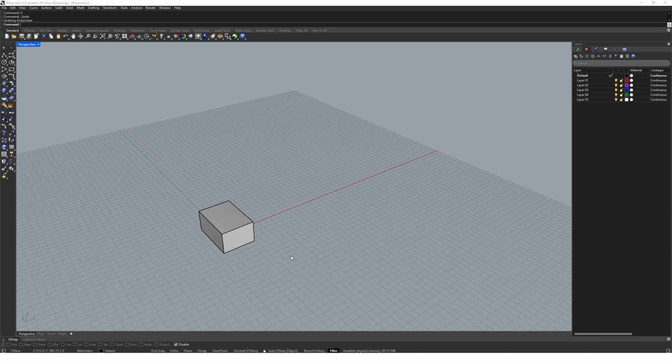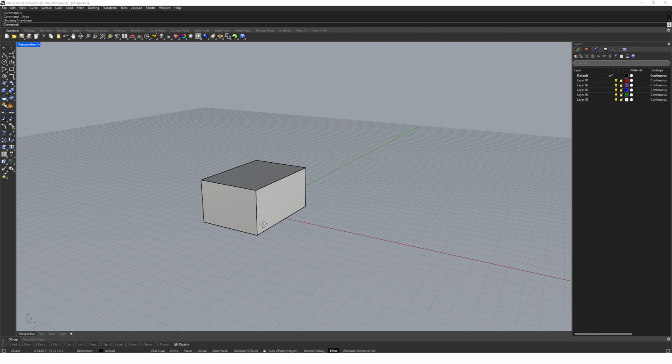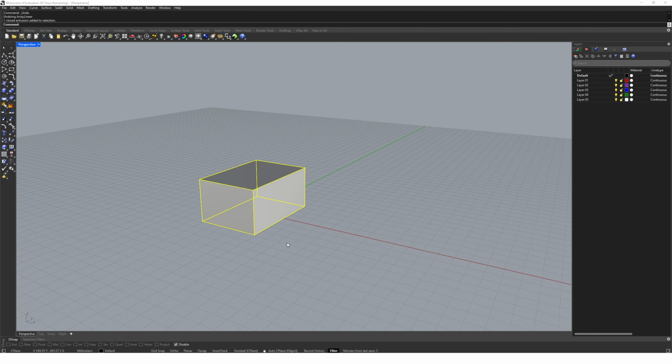Let's touch on a couple of other helpful tools in Rhino we can use to navigate and select and manipulate our geometry. If I select this box, I select the whole thing, but what if I wanted to select the front face only? If I hover over this front face and use Shift, Control, and left mouse button click, I'm actually able to select into the face of this geometry. I could then manipulate the geometry with things like the move command and move that face out on its own. I could even rotate it or use some of our other transformation tools as well.